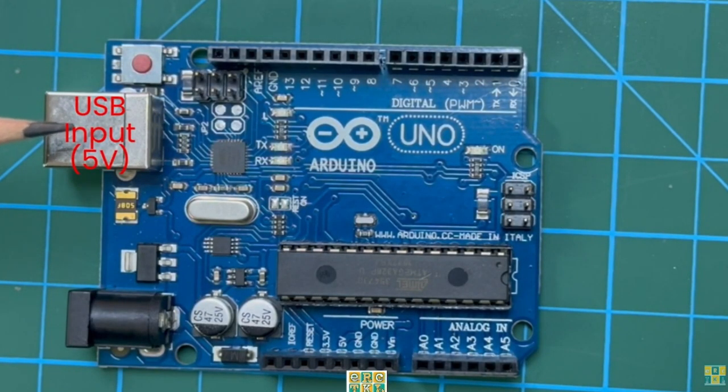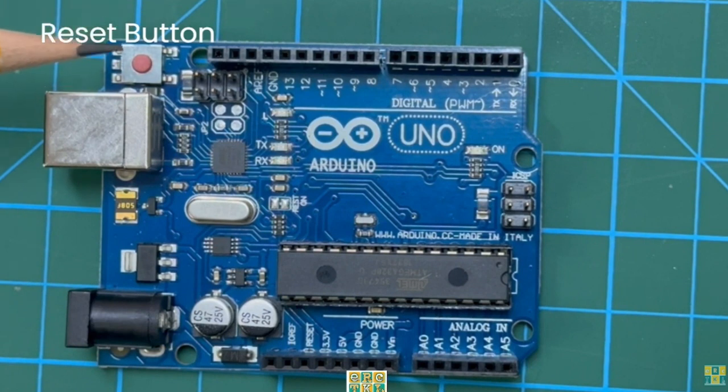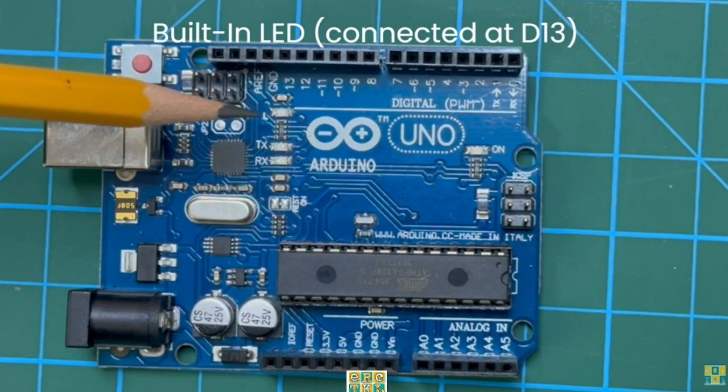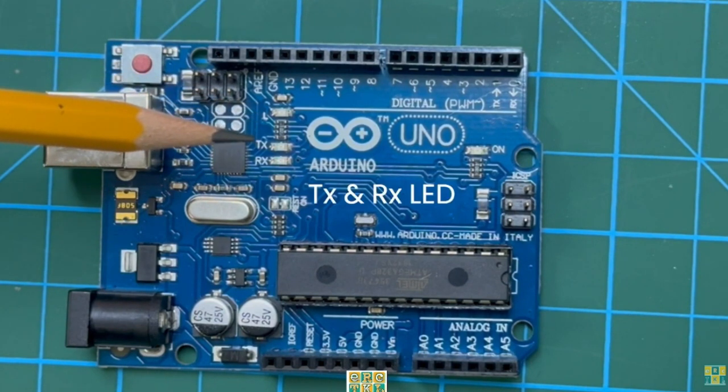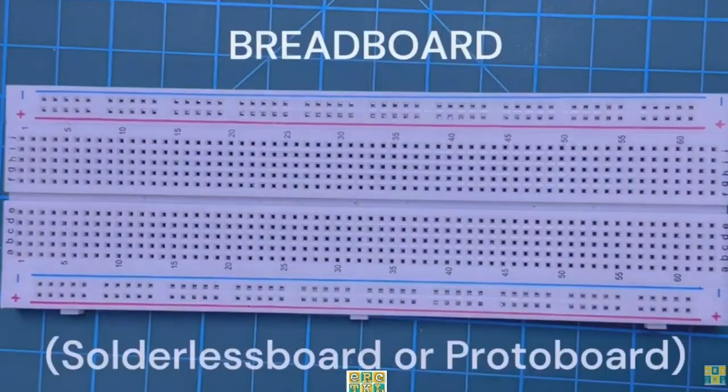And then this part is where we will put the USB input, or you can also use the DC jack. And if you want to reset the program, you can click the reset button. And there's also a built-in LED connected to your digital 13 with letter L. And when you upload or download something to your board, you will see the TX and RX light.